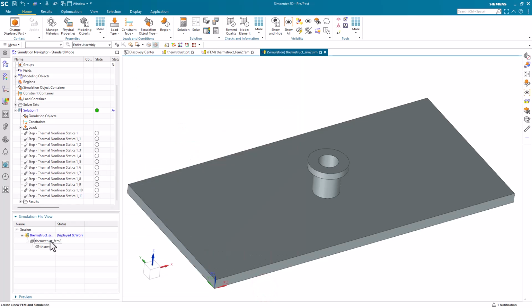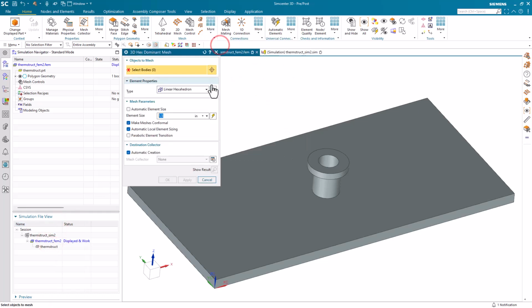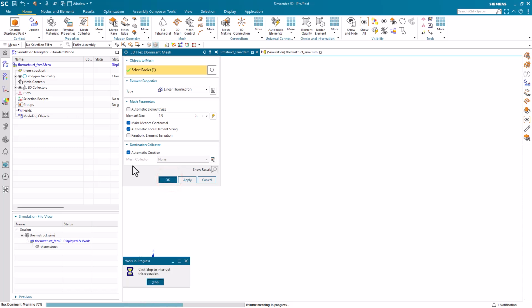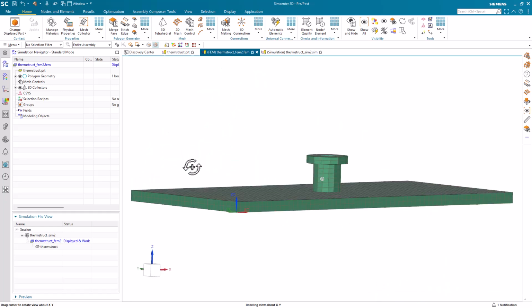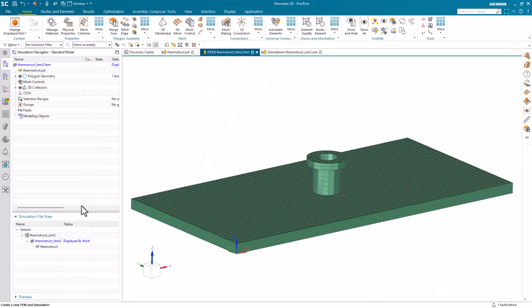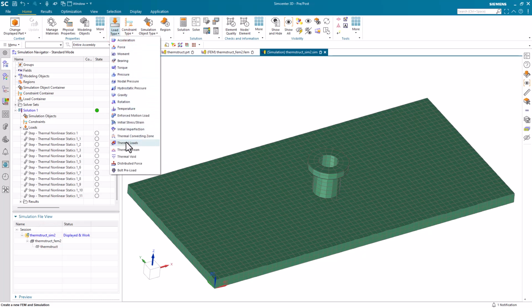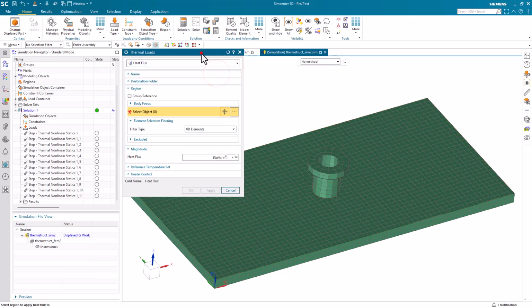All right, now that we have our steps set up, we'll go ahead and put a mesh on the part. And here we'll use the Hex Dominant Mesher. And I'm going to use a coarse element size for this demonstration to speed up the solve. So here you can see we have about 2 elements through the thickness. And I also don't need to apply a material property because by default I'm inheriting the material from the CAD model.